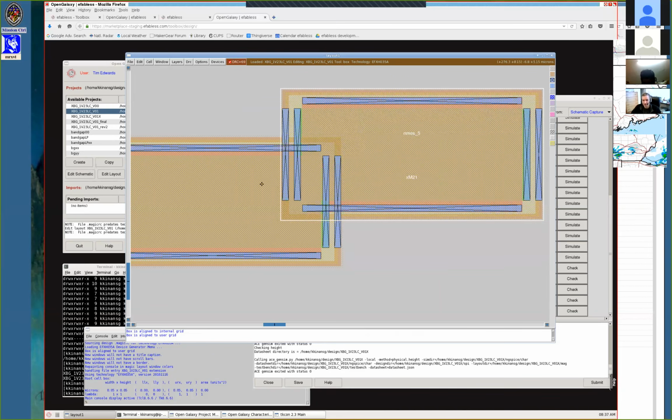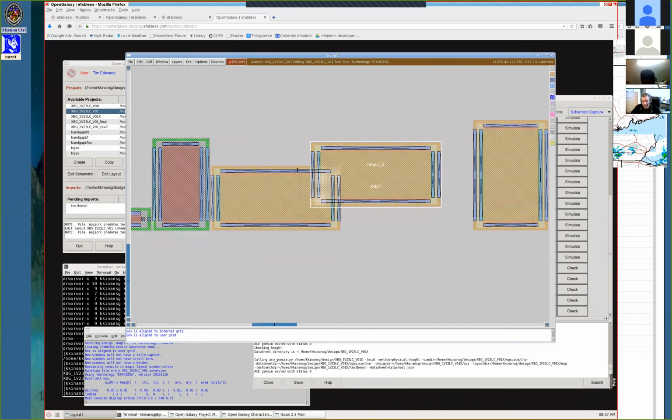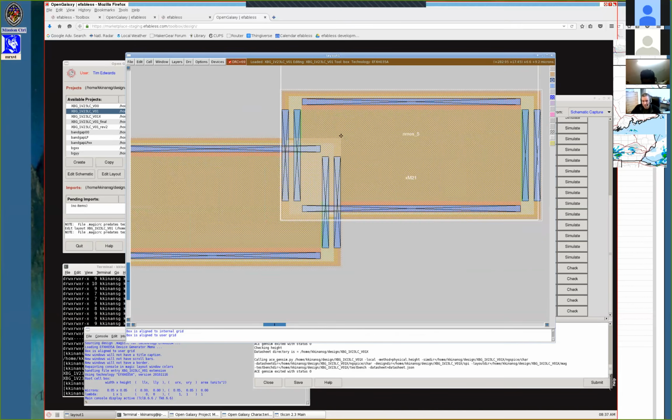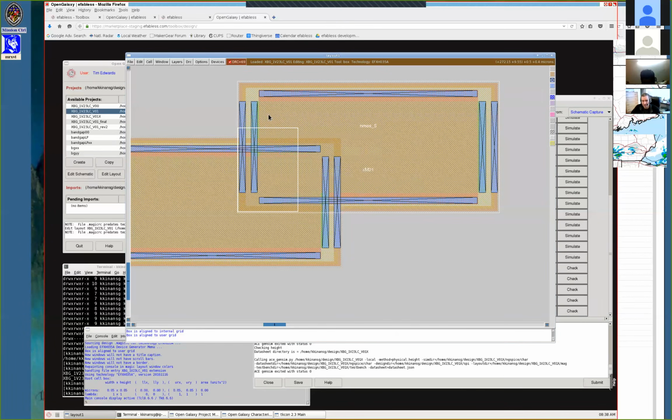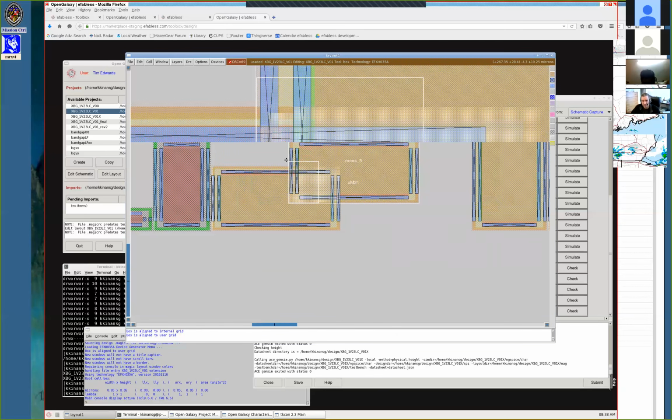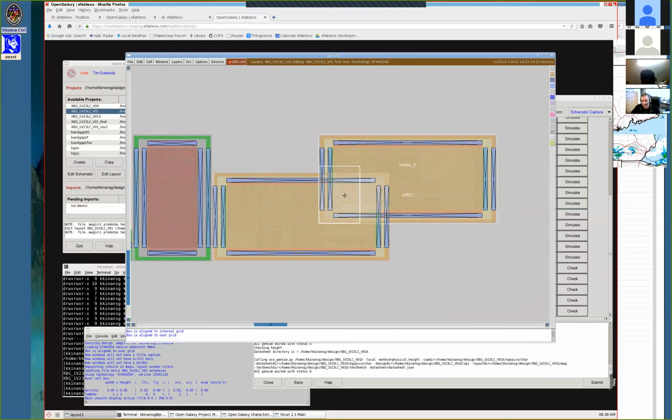and move it until it's overlaying that cell, then you'll see that everywhere you see these white dots appear, that's a DRC error. If you check the DRC listing here, I have DRC 70. That's my DRC count of violations. If I move that cell over, actually I have no idea why the DRC count went down there. There must have been more DRC errors over on the other side that I wasn't looking at. But yeah, you'll see the DRC count change when you do an overlap like that.